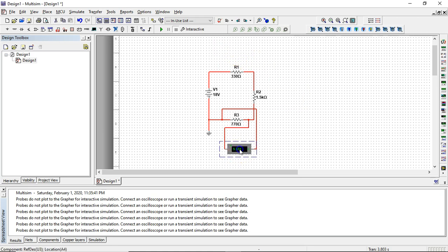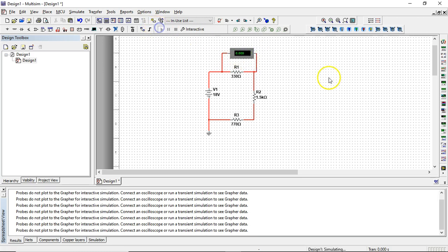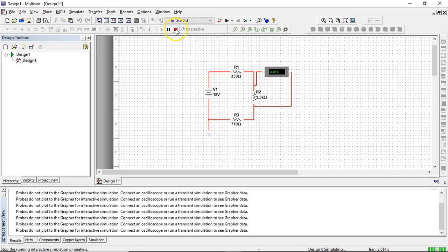But what if we wanted to use an ammeter? This one right here, an ammeter, which measures amps. Well, if I take this guy and I put him on the negative side and the positive side, and I press play, I get a reading of 7.933 milliamps. Great. What if I change it from here to across this guy? Let's go from across component number 2. If I press play, it's 0.016 amps. But we know that in a series circuit, the current stays the same. So something important is going on here.